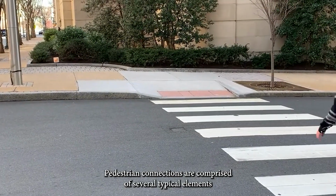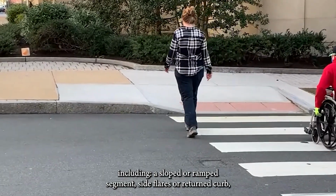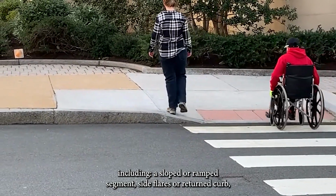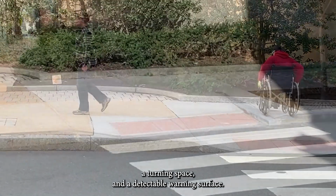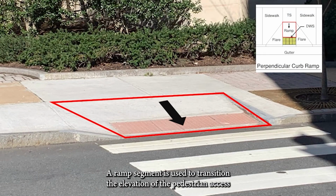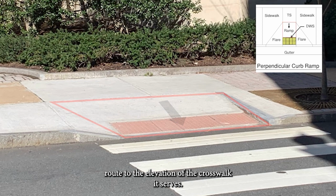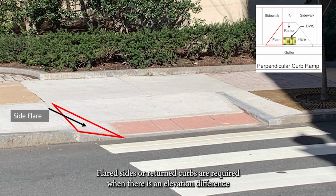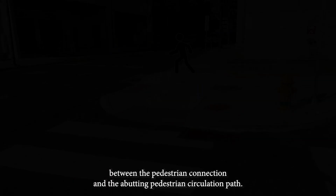Pedestrian connections are comprised of several typical elements, including a sloped or ramp segment, side flares or returned curb, a turning space, and a detectable warning surface. A ramp segment is used to transition the elevation of the pedestrian access route to the elevation of the crosswalk it serves. Flared sides or returned curbs are required when there is an elevation difference between the pedestrian connection and the abutting pedestrian circulation path.